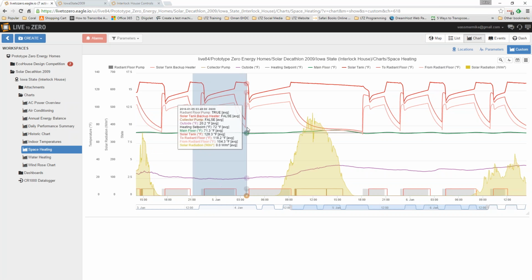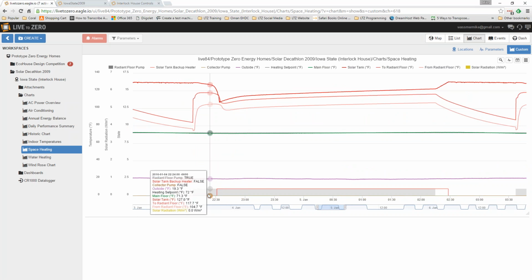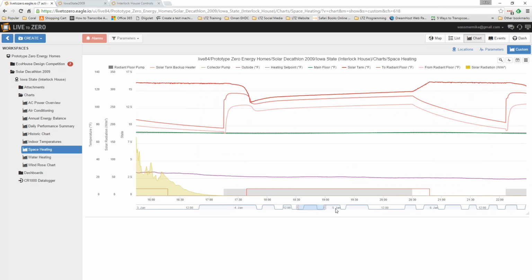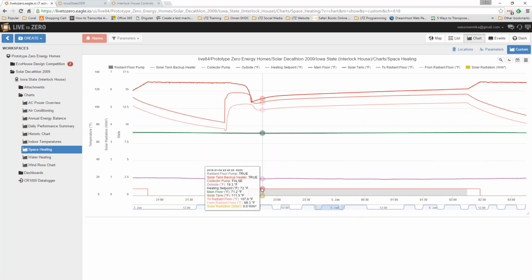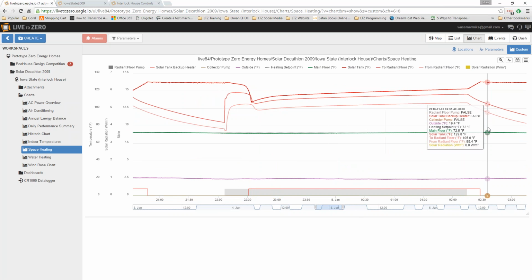And you can see on the chart here, it's a little hard with the scale, but the temperature is still dropping after the heat turns on, and that's because it takes so long for the floor to heat up, because the floor has cooled down in these previous couple hours, right? And so it takes like an hour for the floor temperature to heat up, and then finally the space starts heating up very slowly. And then it reaches 72.5, which is when I have the heat programmed to turn off.